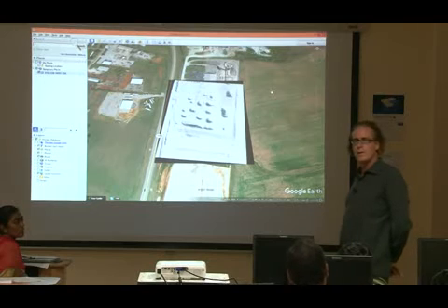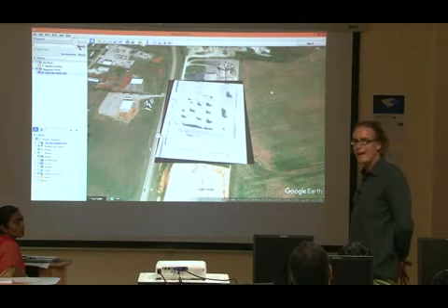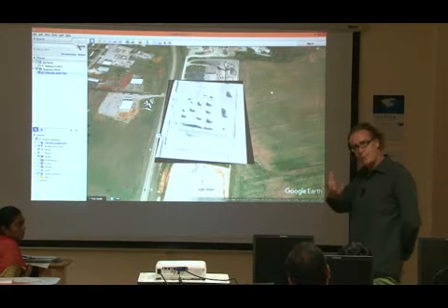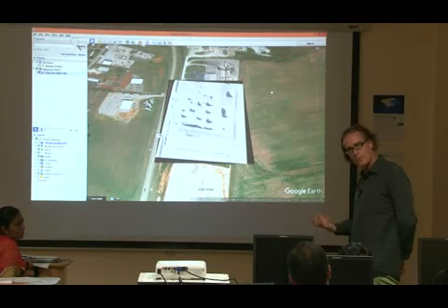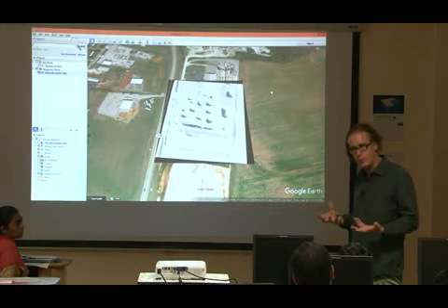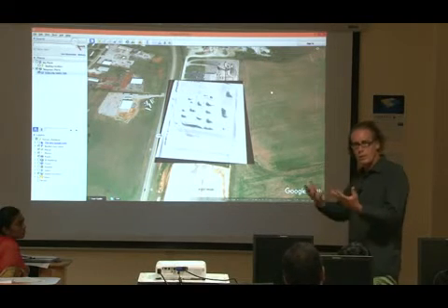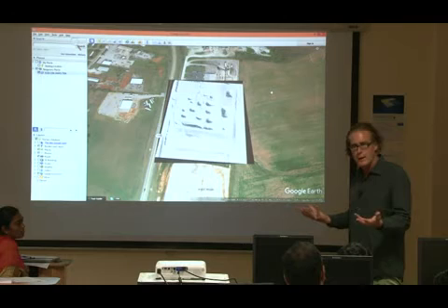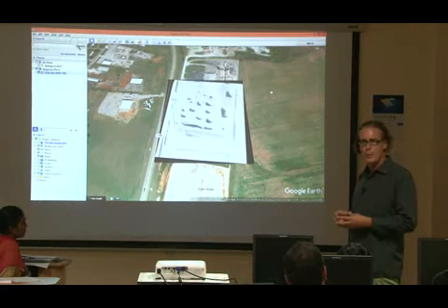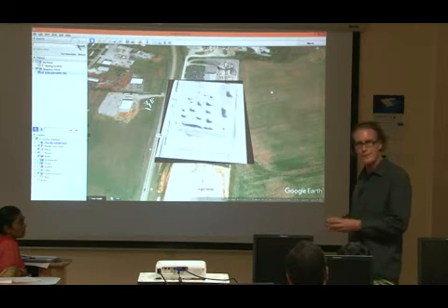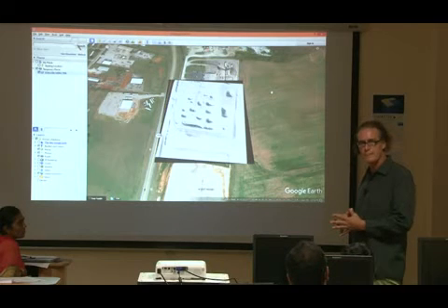Well, the point cloud, as I said, you can add the orthophotos with lascolor, for example. You can add the pictures onto the point cloud, so you have colored points at the end. That's possible. But then you have colored point clouds. How do you exploit colored point clouds? Well, visually it helps you in understanding if the classification is correct when you do visual checking.